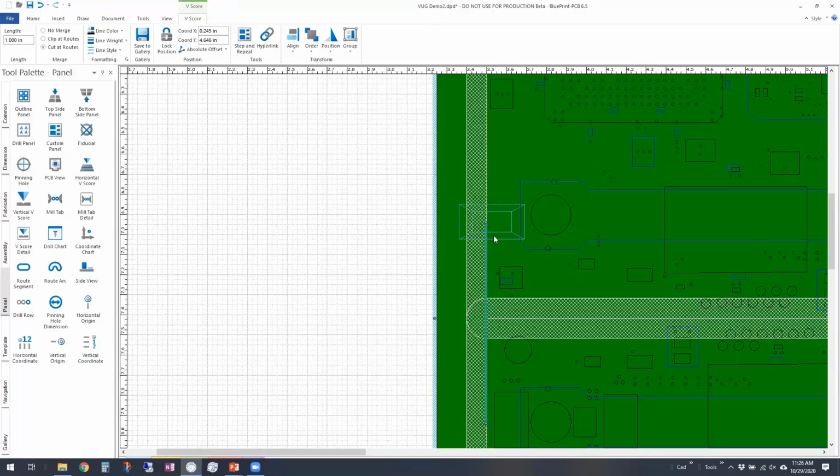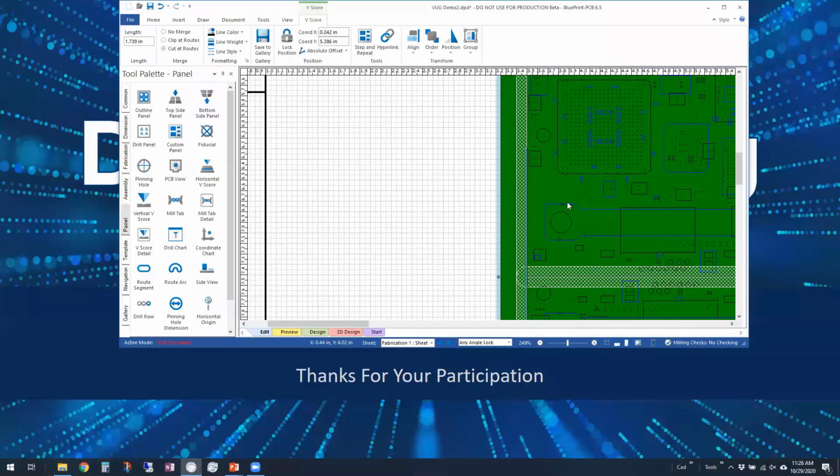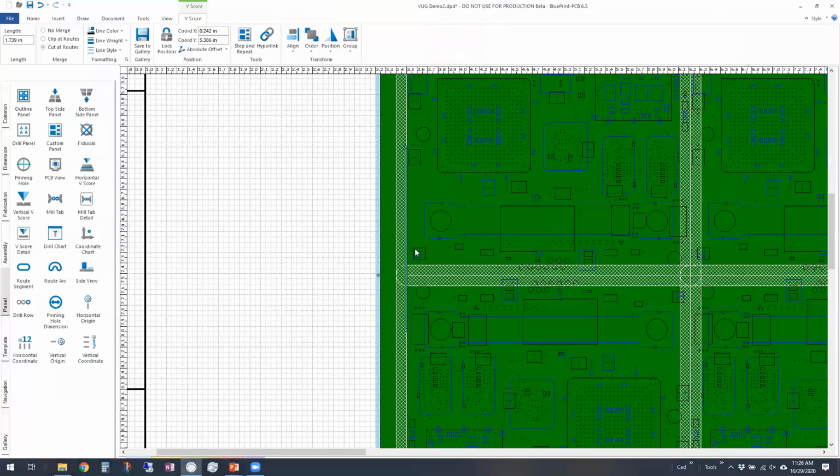And then once I do that, I'm going to zoom out a little bit. It's easier to drag if you're zoomed out. And you notice how it's going from side to side there. Well, I don't really want that. So one of the things I should be able to do is turn on the orthogonal snap so that it locks it to a 90-degree angle.